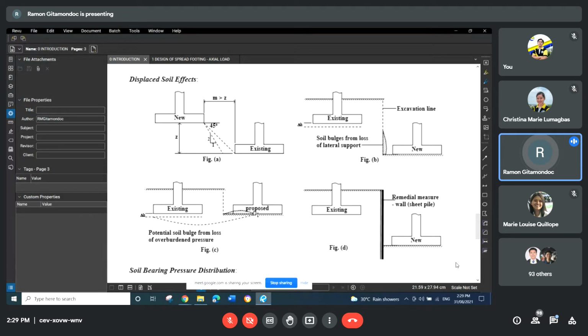or pressure acting downward, no. So if the pressure in the existing foundation is high, it will tend to relieve the pressure laterally, no. So that will cause bulging on the excavation side, and with the soil displaced, it will cause settlement on the existing foundation side.